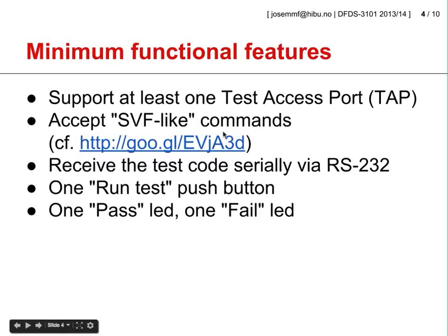The minimum functional features comprise at least one test access port. Our system should also accept a set of serial vector format-like commands. Serial vector format, or SVF, is a test representation format that was developed jointly by Texas Instruments and Teradyne, and you can read more about it on this Wikipedia page. Actually, what is being asked in this coursework is a simplified version of SVF.